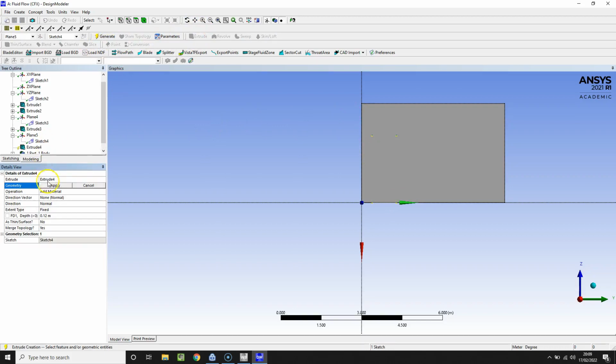This time when I hit extrude, I'm not looking to apply material at all, I'm looking to just imprint faces. So all this will do is create the shape of the door on the outside of the domain, and because of that, I'll have a separate boundary that I can apply a different temperature boundary condition to.